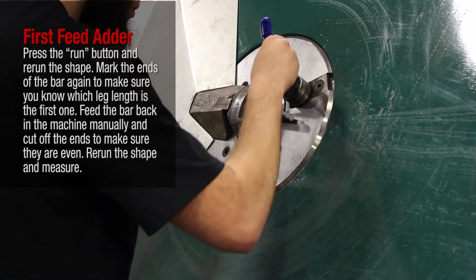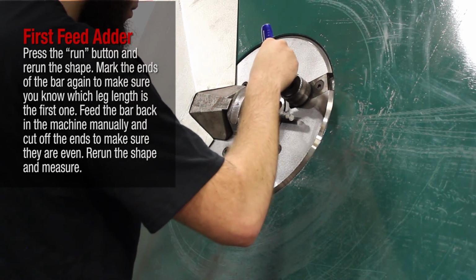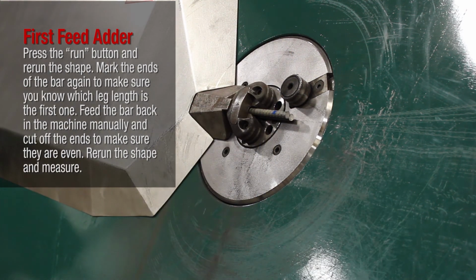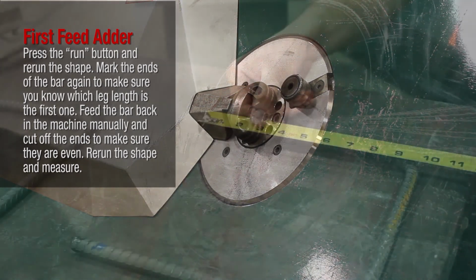Mark the ends of the bar again to make sure you know which leg length is the first one. Feed the bar back in the machine manually and cut off the ends to make sure they are even. Rerun the shape and measure.